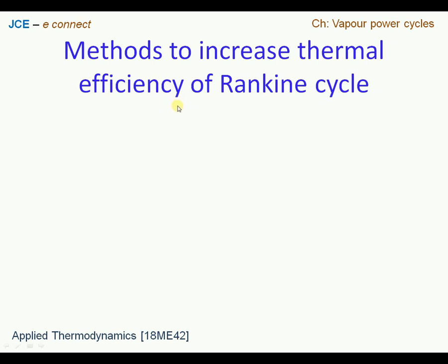Therefore the pressure of the condenser is largely dictated by the saturation pressure in correspondence with the temperature of the cooling medium seen in the condenser.